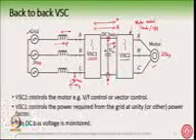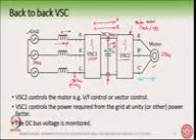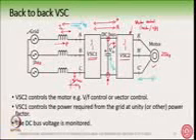Suppose we take a condition where the motor is feeding power back into the DC bus through VSC2, it is regenerating. What will happen to the DC bus? The DC bus voltage will go on rising. And so what will VSC2 do? It will see that the DC bus is increasing at a very fast rate. So suppose the voltage VAG and current IA was something like this previously. Now VSC2 will make the current like this. It will reverse the current.